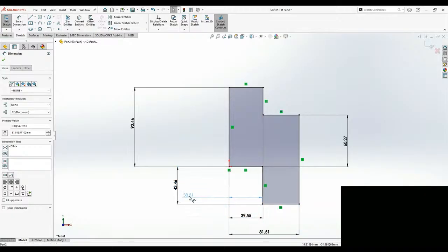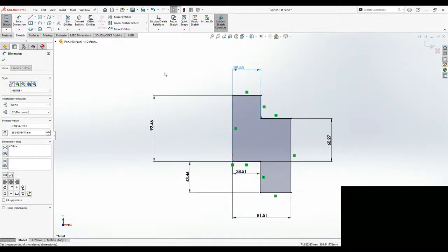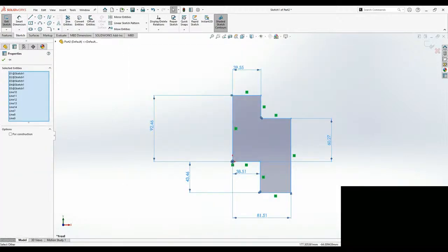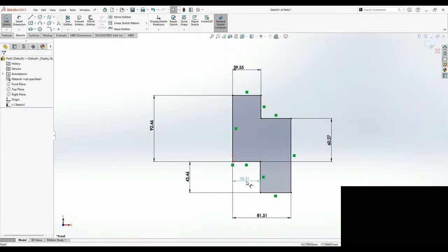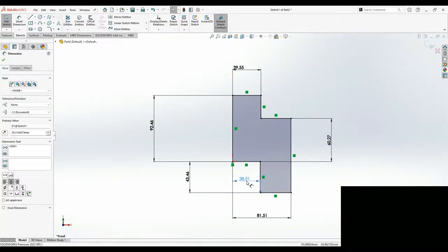And there is something extra. Okay, this should be here and this should be here. I think there is again an auto arrange option. It should be in sketch, not here. Yeah, in the Sketcher workbench, you can just auto arrange all your dimensions.